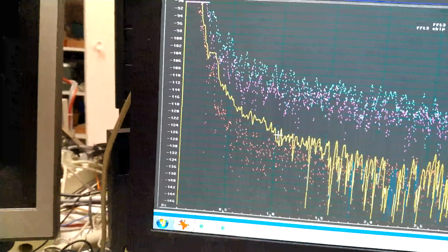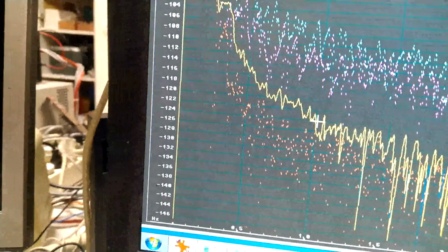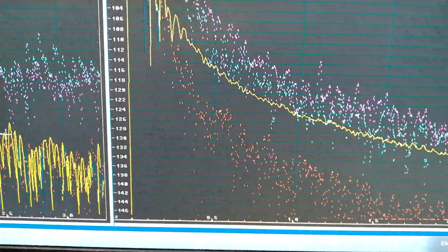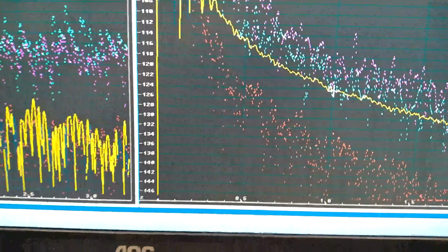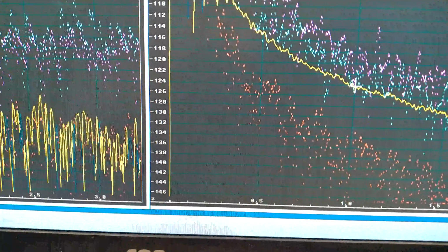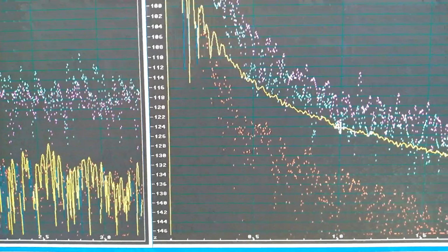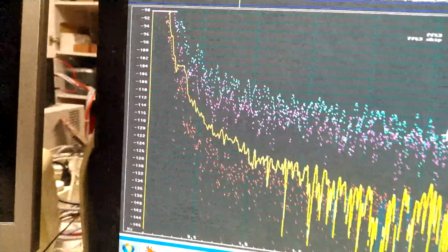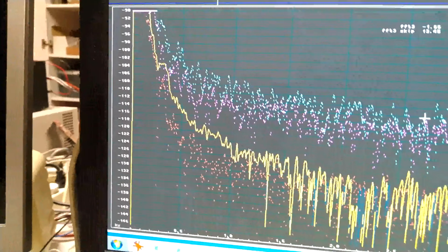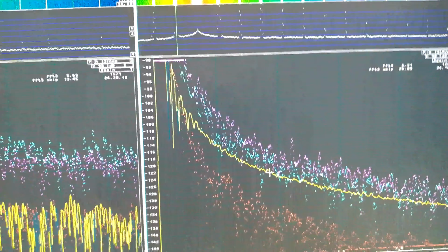I can read at about 1 Hertz minus 124 dBc per Hertz. And for the sound card at 1 Hertz, that's here, I can read also minus 124, but with a much better statistic accuracy. So I can use the SDR IP at wide separations and the sound card at narrow separations.